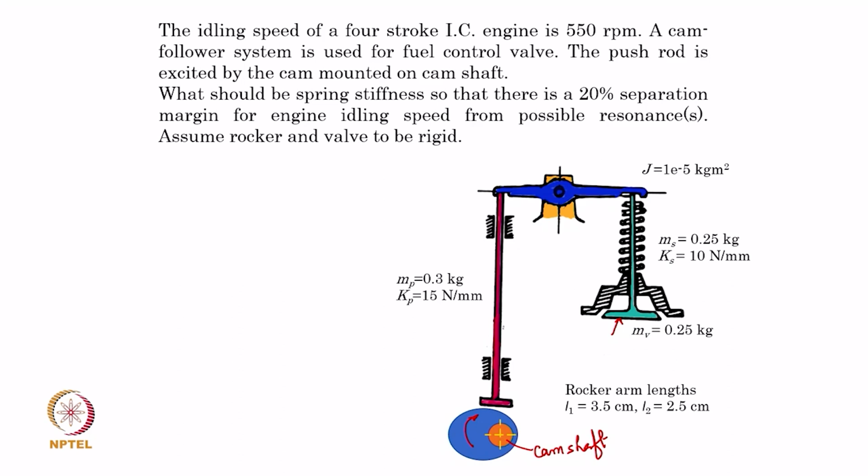So, this push rod is being pushed by the operation of the cam, the rotation of the cam. It sort of uses the leverage that we get here in operating the valve in the cylinder against the spring pressure.